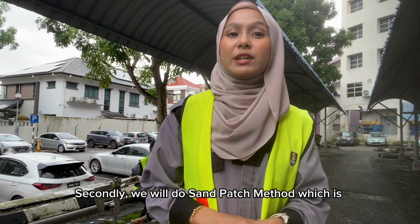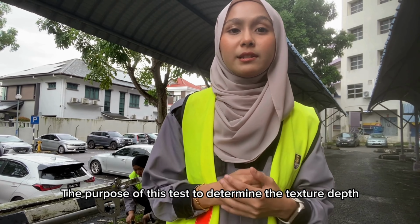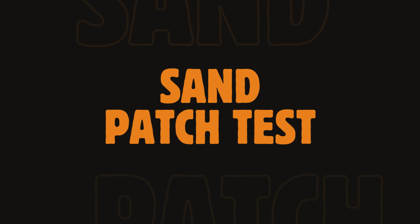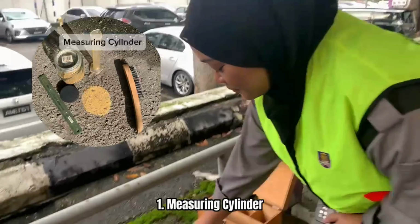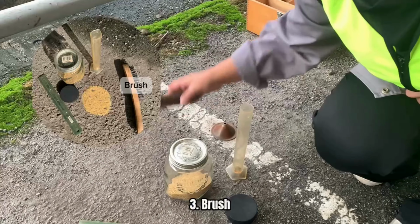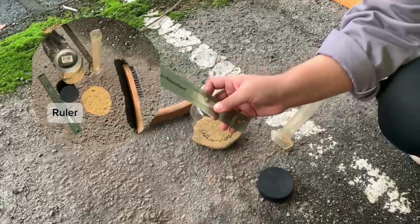Secondly, we will do the sand patch method. The purpose of this test is to determine the texture depth of the road surface, which affects friction and water drainage. Next, for the sand patch test, we need the apparatus, which is a measuring cylinder, flat disc, brush, sand and ruler.